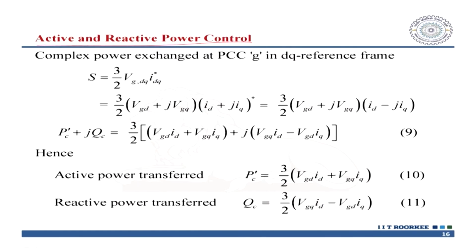because you may be charging the battery. Once you are charging the battery, your charging current has to match the thermodynamics of this battery. So there is a trickle charging mode, a constant current charging mode, and a constant voltage charging mode.